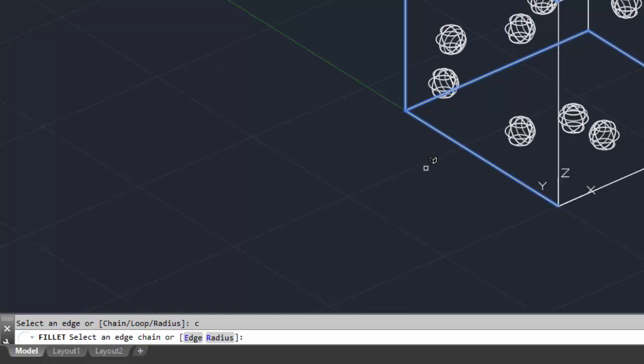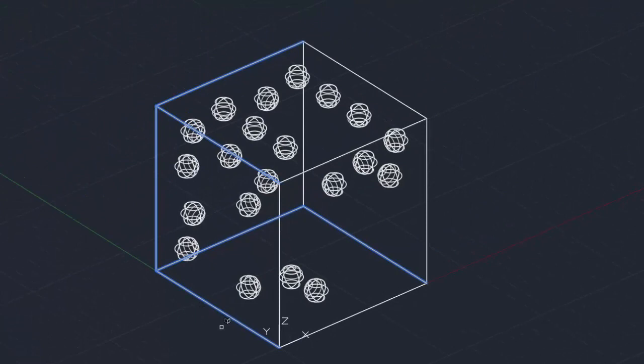Now one thing that I've noticed, and I don't know if this is a bug in the program right now, but you'll see that it's already selected a number of these lines in blue. They're not selected, but it comes up as being selected. I don't know why that is. I don't know if it will happen on yours or not, but what you need to do once you've done that is select the edges. So imagine just left click on that top edge, left click on the side, the bottom, the upright on the back. Do the same thing on these from the front, and they don't go blue, and I don't know why that is. And then each one of these joining lines, the bottom one, the top one, the back, and the bottom back.